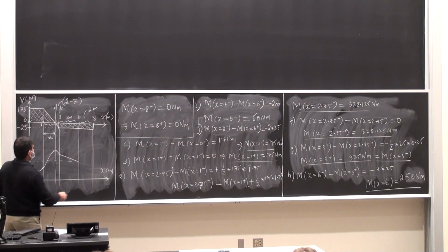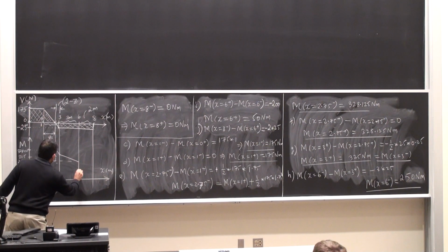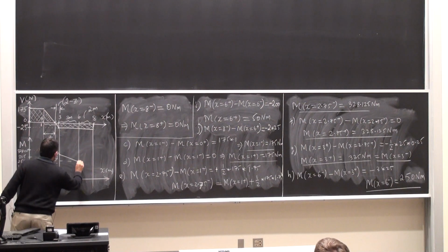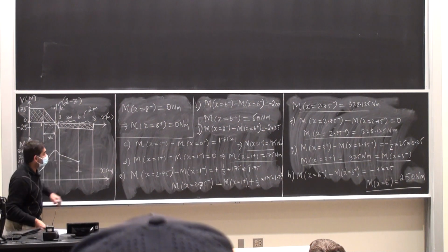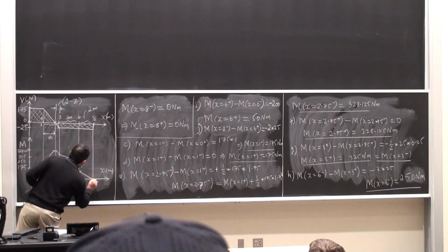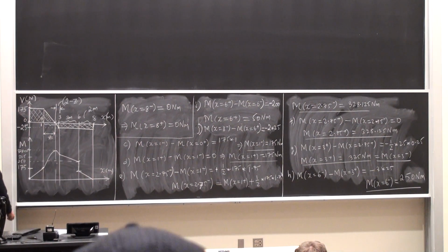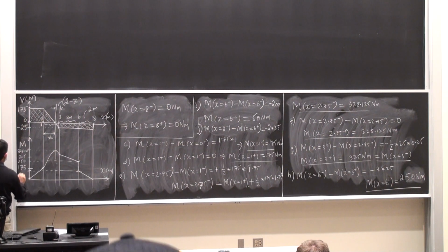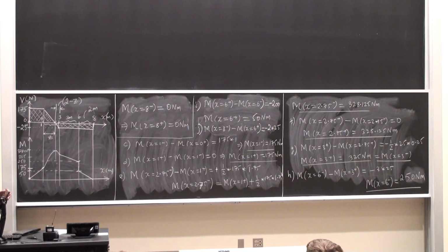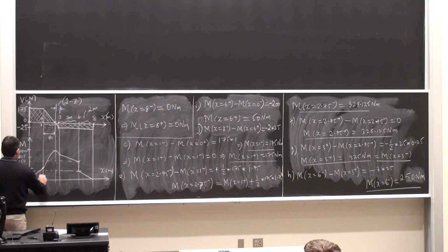That's a jump, I'm sorry, that's a jump right down here. So this is the jump that you see in the bending moment diagram. Okay, this is because of the fact that I'm sitting at x equal to 6 plus. It's dragging me down to 50 Newton meters. And then I go down. Okay, so this is 50. And this entire creature is the bending moment.